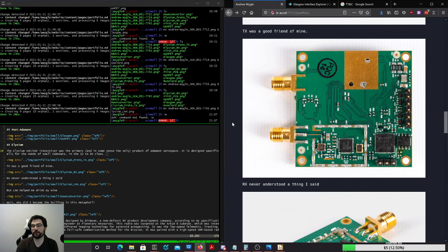And they're both very radiation tolerant because of the physics of how they work. But MRAM, I think mostly for marketing reasons, is dedicated a lot more to high speed, high power than it is to low speed, low power. The problem with FRAM is that it requires extra process steps, and there also seem to be some scaling limitations. It's hard to make it super duper tiny. I think these are on a 140 nanometer process or something like that. It's pretty big for a chip process these days. So we haven't seen it take off the way that MRAM has with things like spin transfer torque MRAM, which is really more targeted at a DRAM replacement.